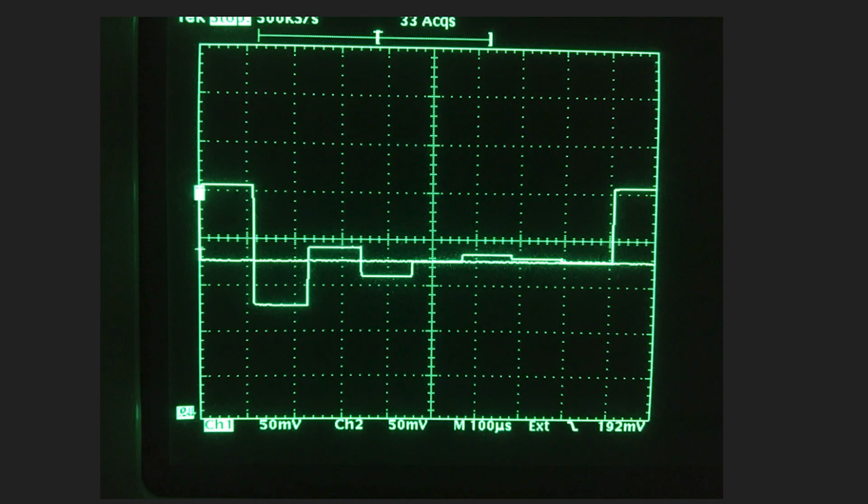So we can see on this oscilloscope here, this is from Mitsuru Yamada's site about his ADC, and the sample voltage here is 1.74 volts. So we're trying to read 1.74 volts. The reference voltage first goes to 2.5, so it's going to be half of 5 volts. We can see here in that far left, it is higher than our straight line reference sample voltage. So our reference is higher than our sample. The weighting bit in this case is going to be a 0. So the highest bit shown by the LEDs is going to be 0.